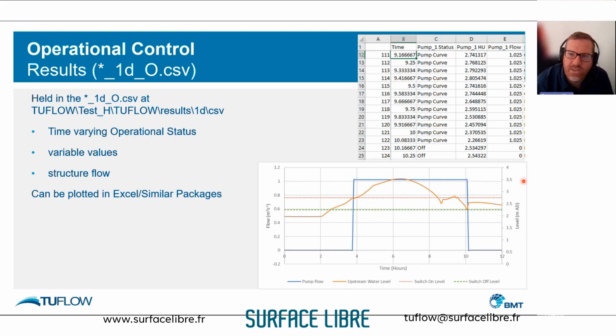As a general rule of thumb, if you're modeling the riverbed in 2D, you want to try and keep the representation of the weir in 2D as well. Same with bridges. You don't really want to switch back into 1D. So you could do it both ways. I suspect you would be able to get similar-ish answers, but the recommendation would always be to keep it in the same dimension. Okay. Yeah, that transfer of momentum across the 1D, 2D linkages would be valid in that instance too. Less important, but yeah.